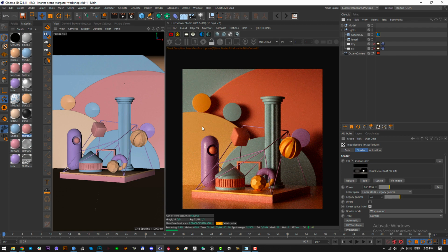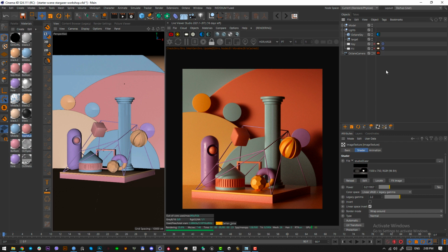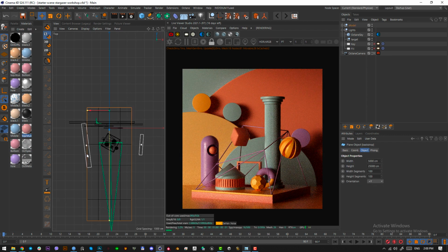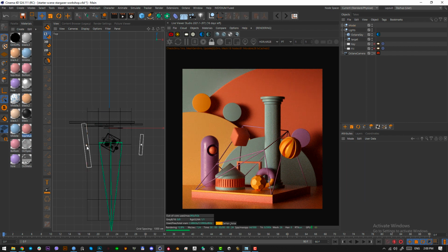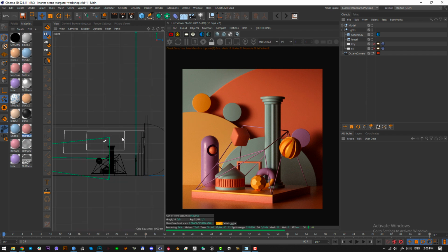on our scene. As you can see, it's coming from the light, it's lighting this part a bit, and leaving this part in shadow. So if you press F2 while here and zoom out, you can see that we have two lights. This is the key light, the one on the left. It's big, soft, and strong, and we have a fill light that's much less intensity. So go F3 just to see how these lights are positioned. They're coming from the top, targeting the bottom.